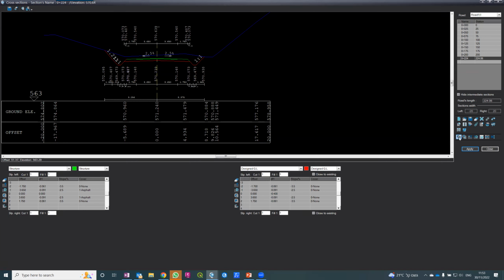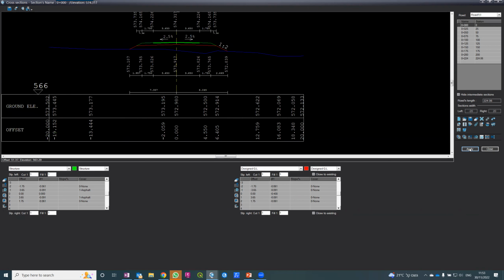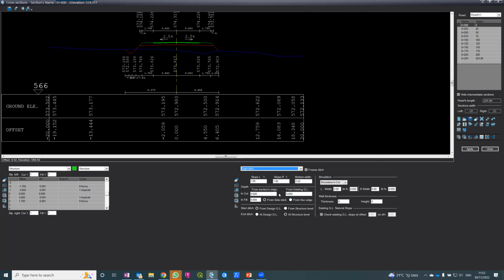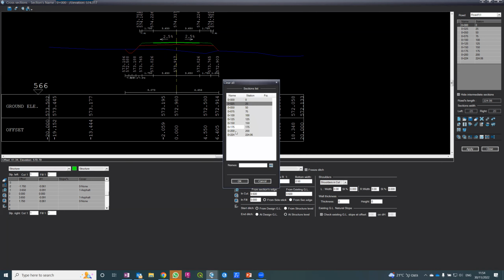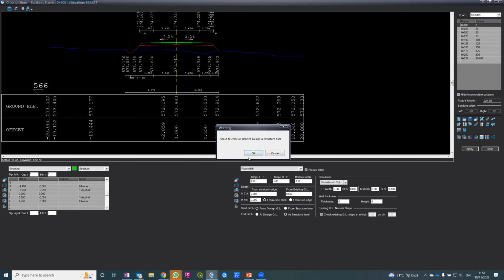Now, what I'm doing, I'm using the same methodology. See, this is the fill. So, okay, this is fill, but I told the software if the fill is lower than 0.6, also create a ditch. I did it in the ditch definition. So let me project it all over.